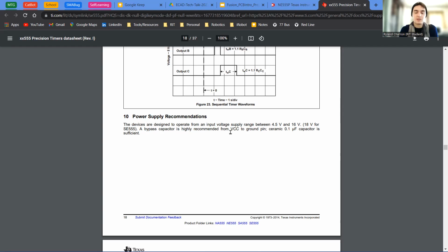It just happens sometimes on PCBs. There's many reasons that could cause it, but you don't want it to cause a change in the behavior of your circuit. So the capacitor just catches that. It's a really small capacitor, so it's for high frequency signals. It'll just quickly discharge or recharge and not affect your circuit. So it's basically a little low pass filter that we're adding to VCC in front of the power to the device.